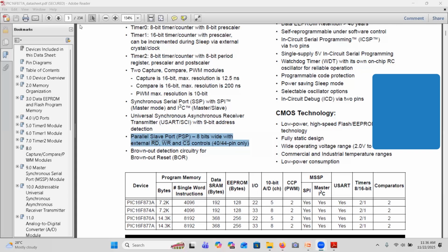As an experienced person, the architect or embedded system engineer should decide which we can go for. Okay, he wants to exchange information between modules. Since it is automotive, we can go for CAN because it is very robust and proven. Some other customer comes, I need to have steering wheel buttons in my steering. When I press that button, something should happen. Immediately that embedded system engineer thinks, okay, this is a little bit slow operation, we can go for LIN, which is lower speed than CAN. So these decisions will be taken by the embedded architect, that means the product architect or an embedded system engineer. If it is a small scale, the embedded system engineer himself will decide that.